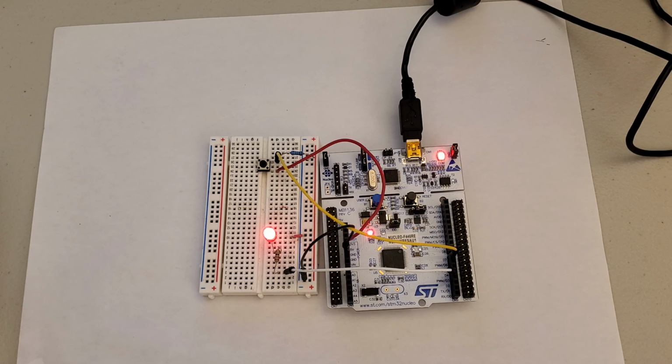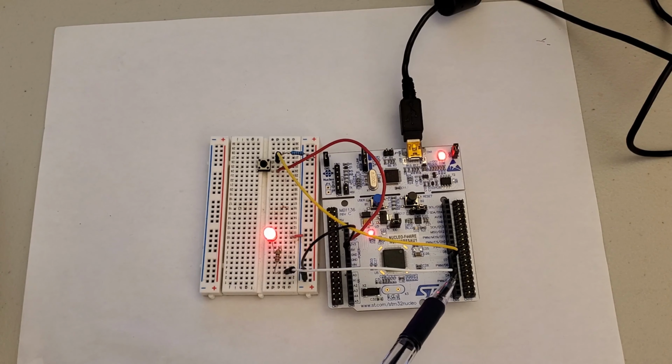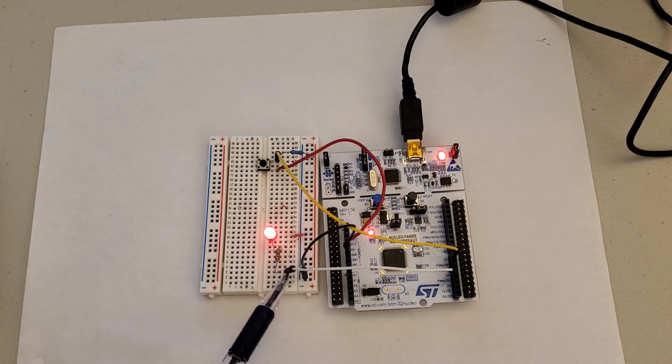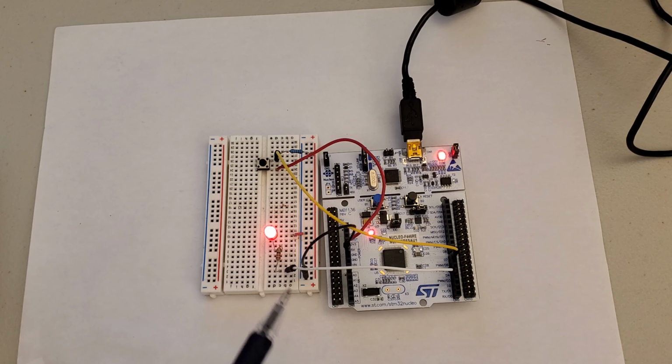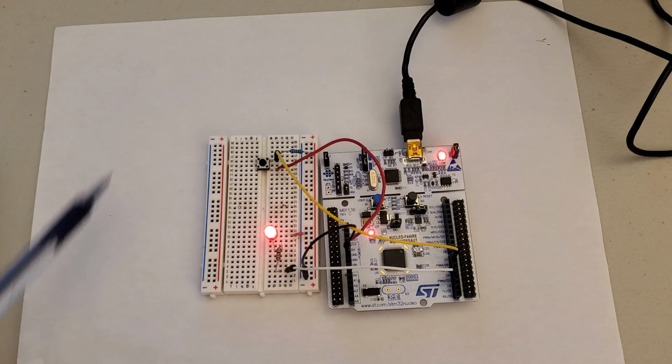The interrupt handler function sends high or low voltage to the pin that is attached to the LED diode and the resistor that limits the current that flows through the LED diode. We use this pin D4 as an output pin, and the function will send high or low voltage to this pin that will turn on or off this diode. I will explain this circuit later on in this video tutorial.